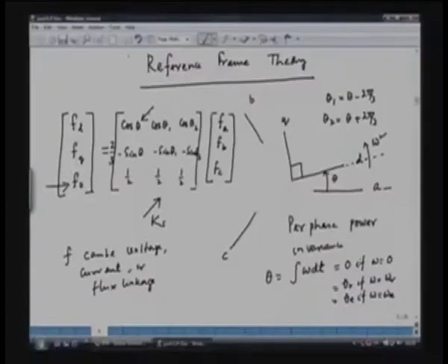If the speed is the rotor speed, theta is the rotor angle with respect to phase A of the stationary axis. If omega is the synchronous speed, theta is theta e, which is the synchronous reference frame angle or the angle of the synchronously rotating flux vector.